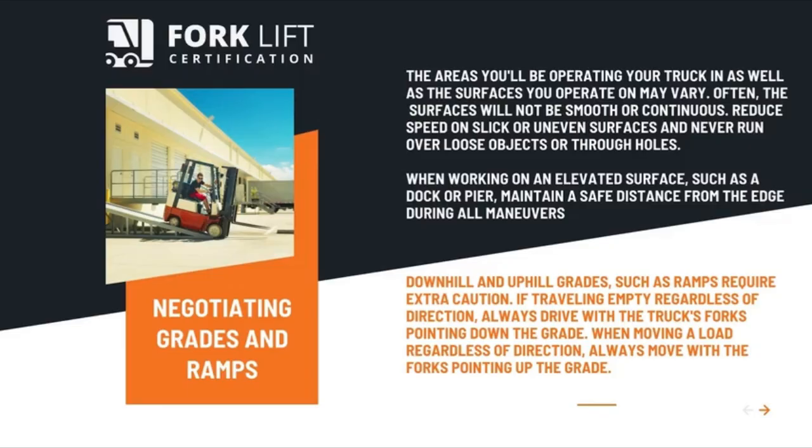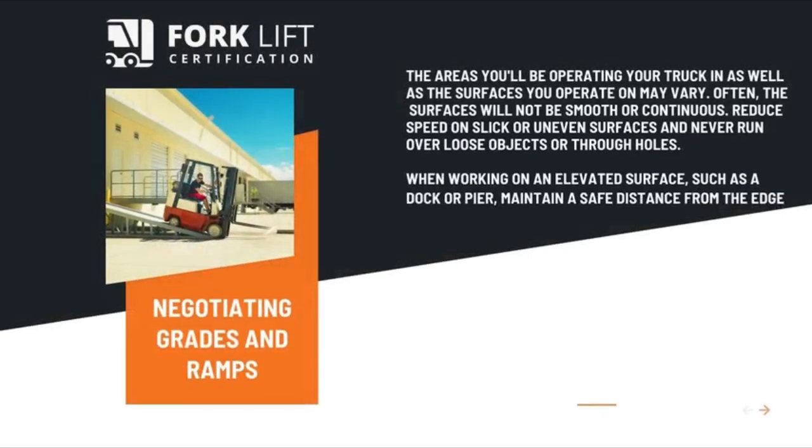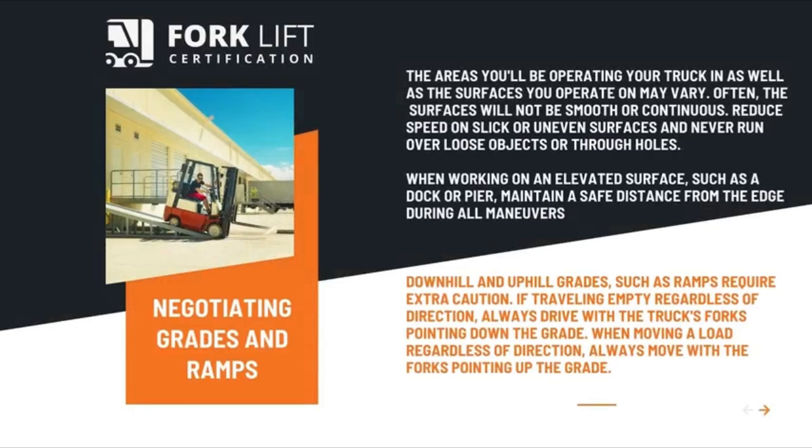When working on an elevated surface, such as a dock or pier, maintain a safe distance from the edge during all maneuvers. Downhill and uphill grades, such as ramps, require extra caution. If traveling empty regardless of direction, always drive with the truck's forks pointing down the grade. When moving a load regardless of direction, always move with the forks pointing up the grade.